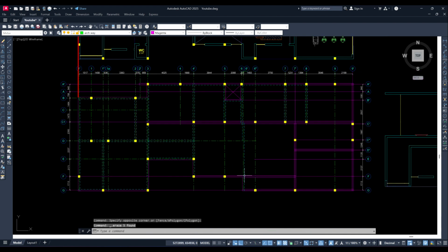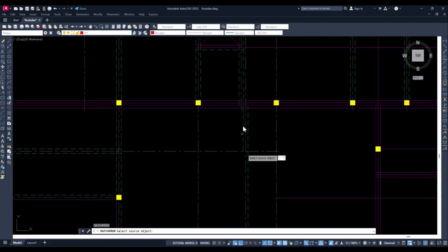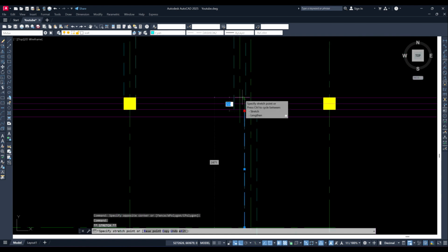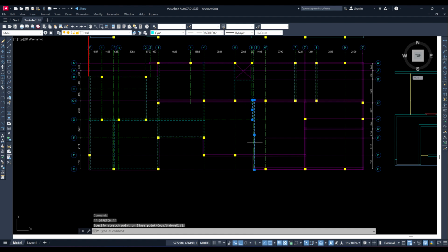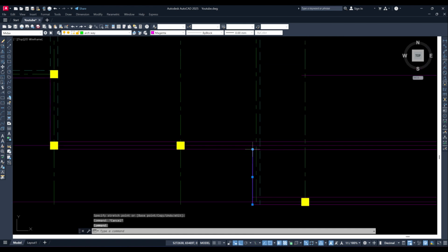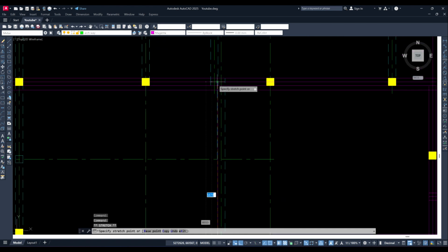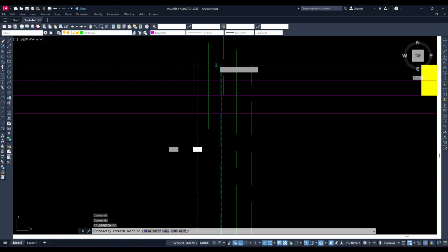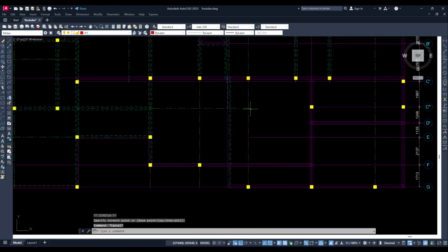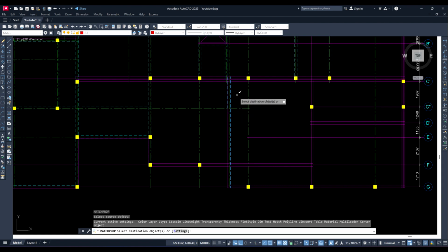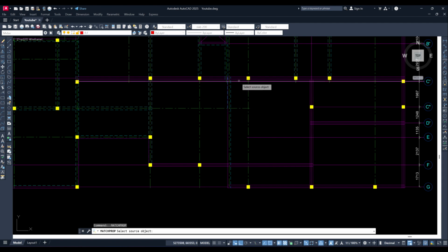for whenever I have a discontinuous slab or there are no slabs in the opposite direction. I use that color to let whoever is reading the drawing know that there's no slab or it's a discontinuous beam. Since it's a roof, I assume everything is voided. So I'm making everything magenta.